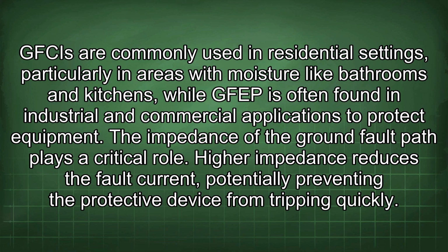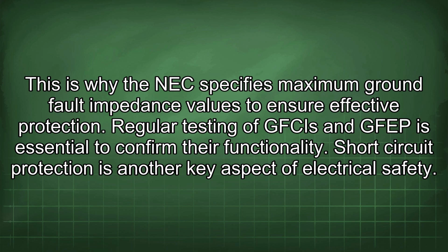The impedance of the ground fault path plays a critical role. Higher impedance reduces the fault current, potentially preventing the protective device from tripping quickly. This is why the NEC specifies maximum ground fault impedance values to ensure effective protection. Regular testing of GFCIs and GFEP is essential to confirm their functionality.